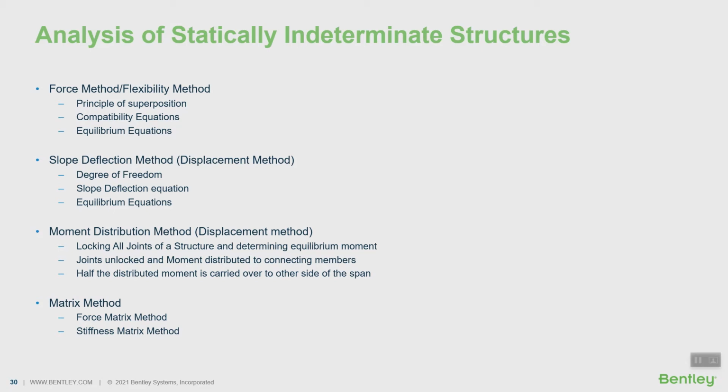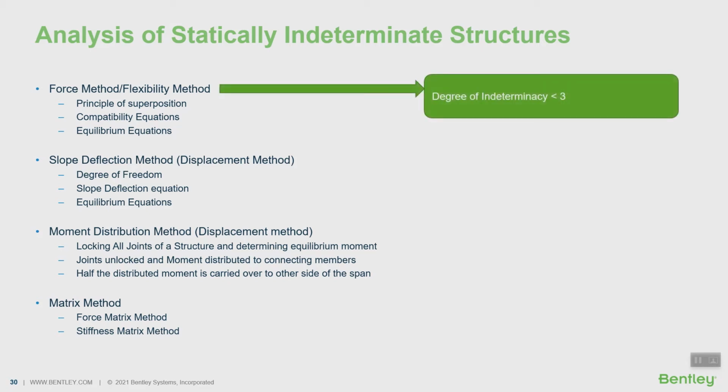Although the structural analysis is complex in comparison to determinate structures, the indeterminate structures generally have smaller internal stresses and deflections for the same loading. Methods for analyzing statically indeterminate structures are listed here. The force method is not suitable for very highly indeterminate structures. In this method, the required additional equations are formed by writing equations to relate the unknown forces or moments in the structure.